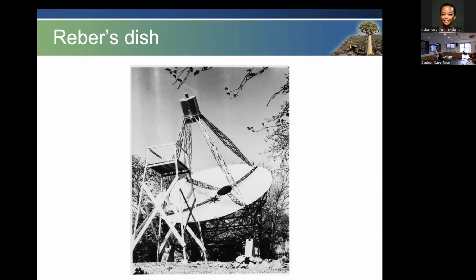Reber was quite a remarkable person. Dish antennas were not a big thing in the 1940s, and he built one in his mother's backyard, largely on a wooden frame, obviously with metal reflecting surfaces, and a sort of microwave waveguide feed. It was a jam jar with a bit of wire in it, basically, but it was quite a thing. And then, of course, the electronics, the amplifiers and everything that went behind it. But it was very early on that the concept of dishes came along. And he did work at higher frequencies. He was working at several hundred megahertz.